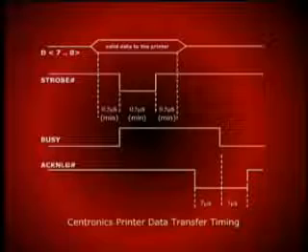The interface will typically use two 8-bit parallel output ports of the CPU, one for the ASCII value of the character byte and the other for the control byte. It also specifies an 8-bit parallel input port for the printer status to be transferred to the CPU for knowing whether the printer is ready to accept the data or not, or other status signals in a similar form.